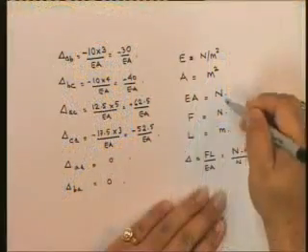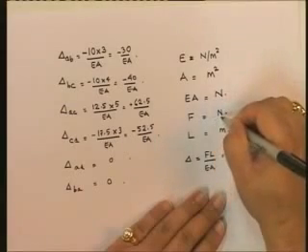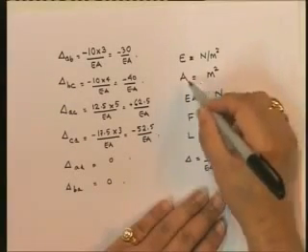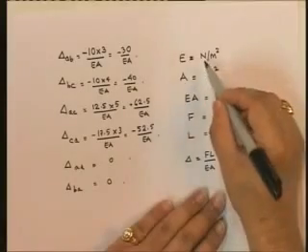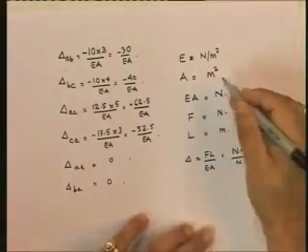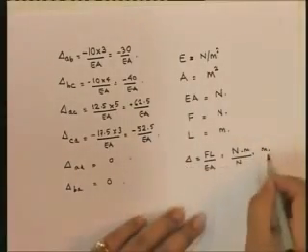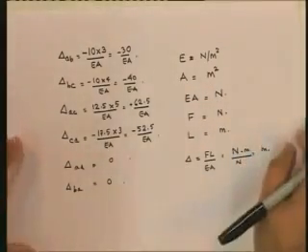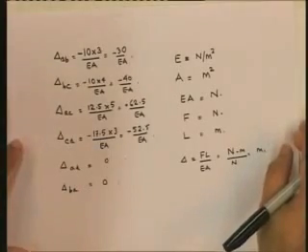Here I'm not doing that, however I am just trying to state that you need to bring everything down. If you want to make F in kilonewtons, then EA also should be in kilonewtons. If you make the area into millimeter squared, then E also needs to be in Newton per millimeter squared. Consistent units will ensure that your delta will be in millimeters. So as long as you are consistent, you shouldn't have a problem with units.